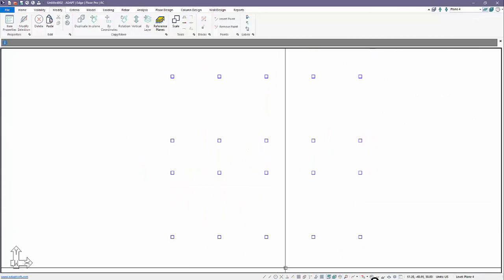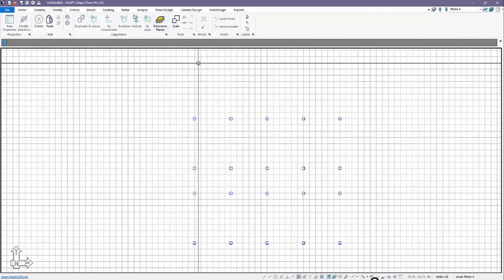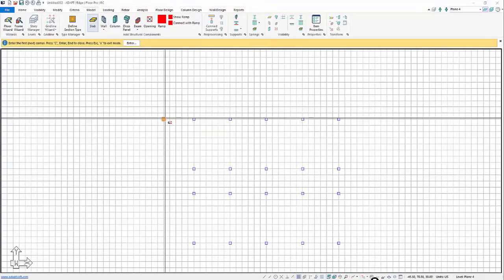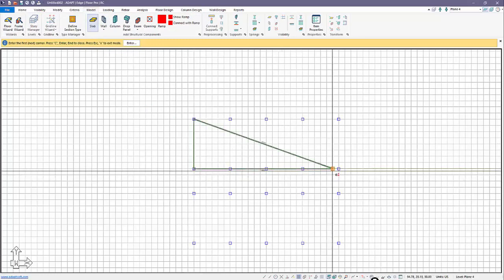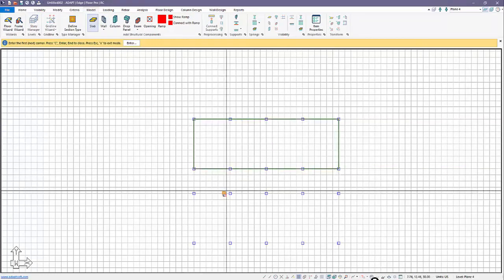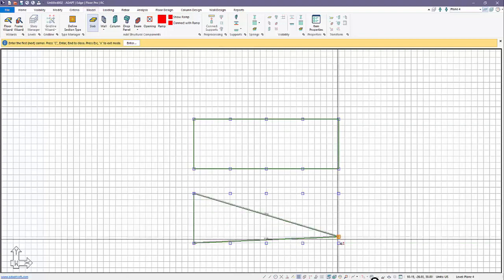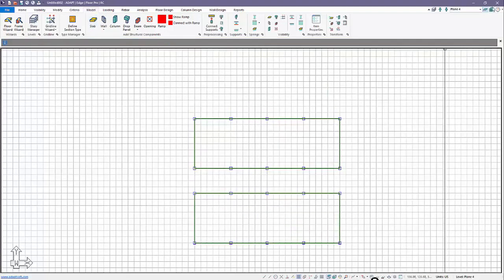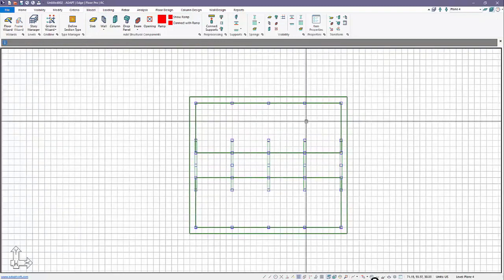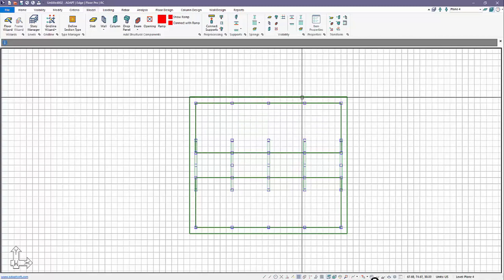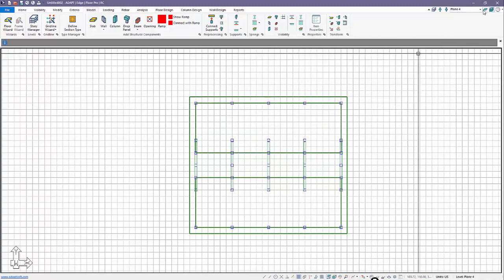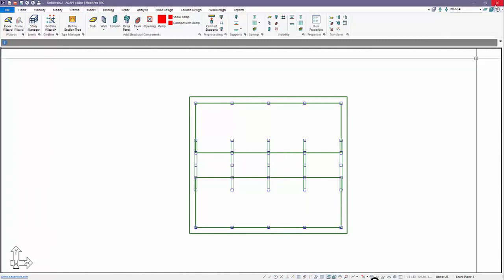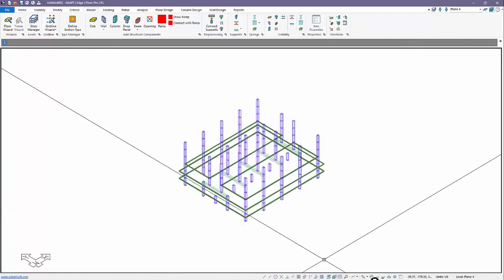We're going to create 2 slabs. Okay, so we'll model a slab region. So the building basically splits at the level 4 and above. There's slab region 1 and slab region 2. And you'll notice this is a 10, 20, 30 foot span there. So that's fine. So ultimately our final product looks something like,